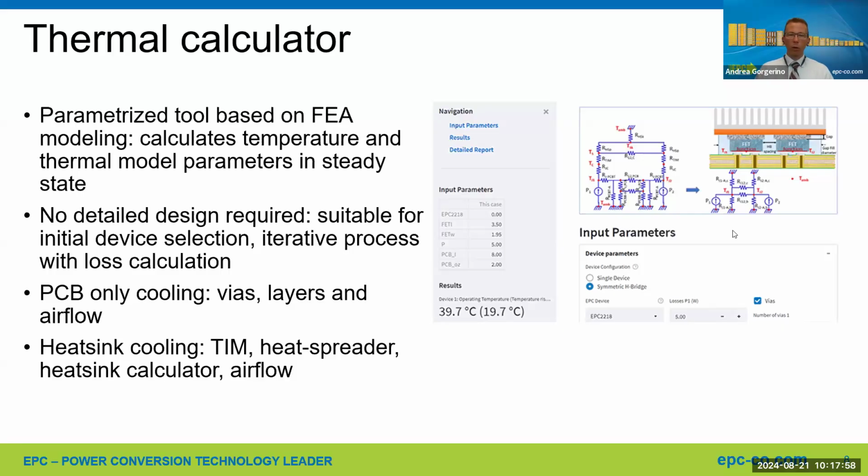What this tool allows you to do is get results without having a detailed design. To use finite element analysis tools, you need to have a real PCB layout implemented, right? Or a heatsink or anything, a real design. In this case, you can put in some parameters for your design, but you don't need the real design. So you need a thermal concept, you don't need a full thermal design, and what you get as the result is basically the analysis of that thermal concept.